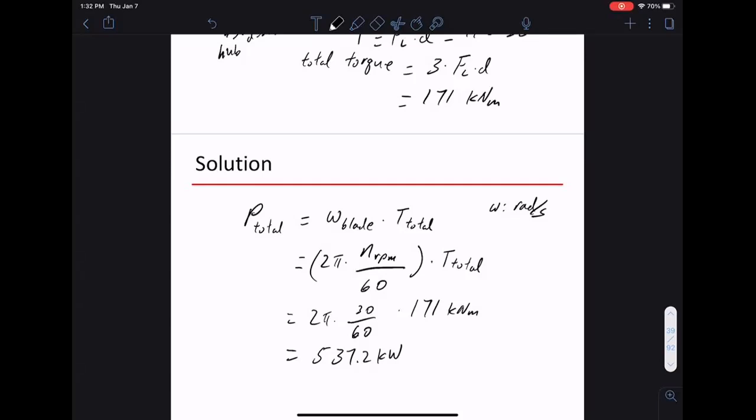What determines the speed of rotation is the shape of the blade, the weight of the blade, the speed of incoming air, and all those kinds of complicated factors. So for us, we'll summarize it into the speed of rotation and the total force, or the lift coefficient. It definitely matters, but getting to that requires a lot more work.